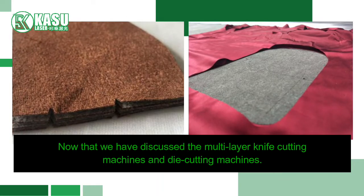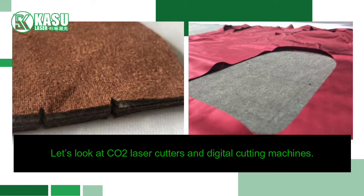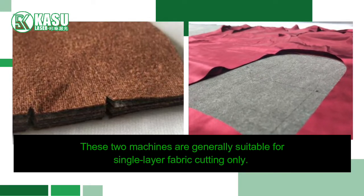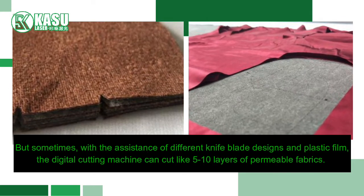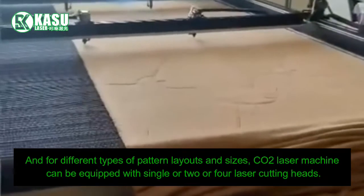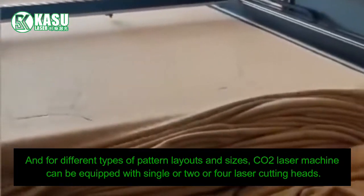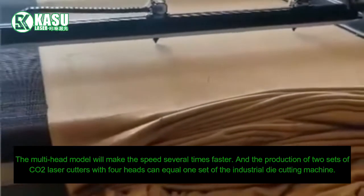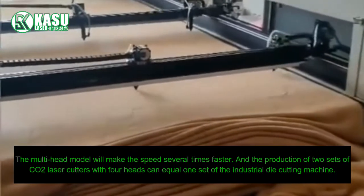Now that we have discussed the multi-layer knife cutting machines and die cutting machines, let's look at CO2 laser cutters and digital cutting machines. These two machines are generally suitable for single-layer fabric cutting only. But sometimes, with the assistance of different knife blade designs and plastic film, the digital cutting machine can cut like 5 to 10 layers of permeable fabrics. And for different types of pattern layouts and sizes, CO2 laser machines can be equipped with single, 2 or 4 laser cutting heads. The multi-head model will make the speed several times faster. And the production of 2 sets of CO2 laser cutters with 4 heads can equal 1 set of the industrial die cutting machine.